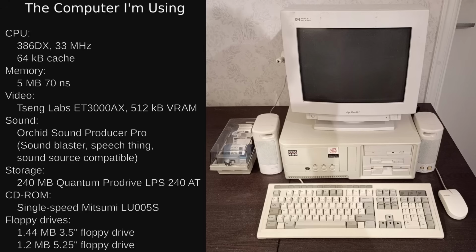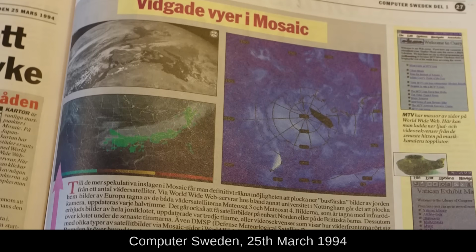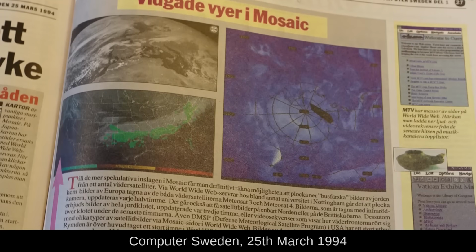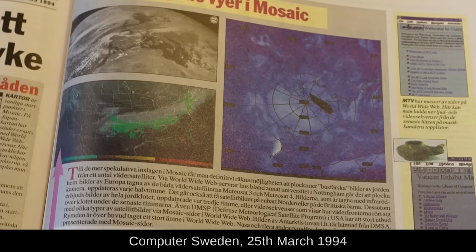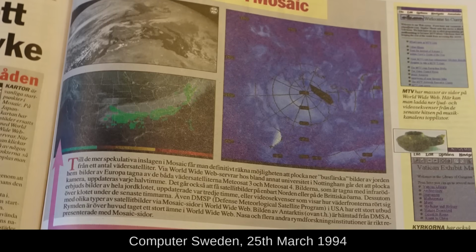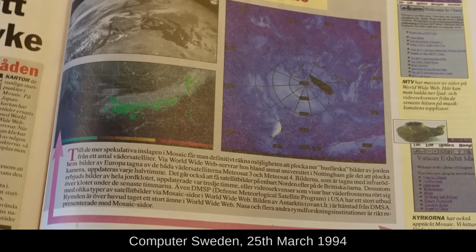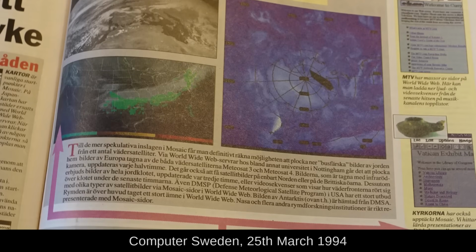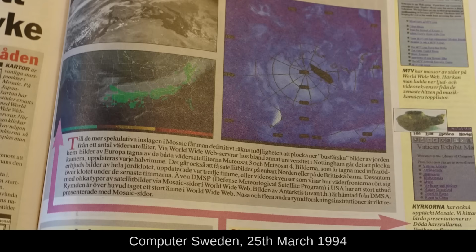When reading about the World Wide Web, I saw that there's a website that could show you recent pictures of the Earth, and I wonder if I could do that too. With some digging, it seems the answer might be yes. Since the 60s, the National Oceanic and Atmospheric Administration of the USA, or NOAA, has had these satellites up in the sky that constantly beam down what they see in real time. It's sent on a VHF band with frequency modulation, and the actual data signal is a fairly low bandwidth audio signal. After scouring BBSs and pestering radio amateurs, I think I figured out what I need, so let's just run through it.